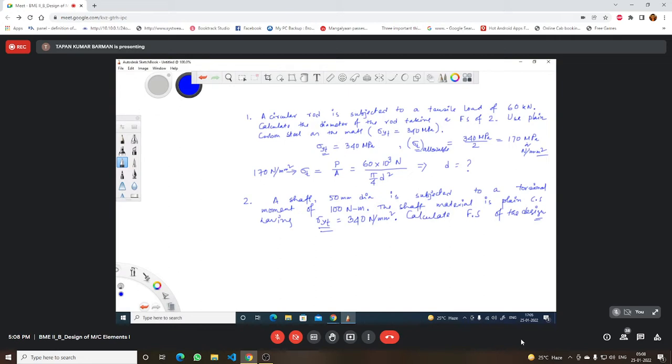We should have the strength information when we are discussing strength. For the first problem, yes, we have the strength value, we may compare that, and from there calculate the dimension. For the second problem, we need another piece of information: what is the strength in shear at the point of yielding? That information should be available to me.